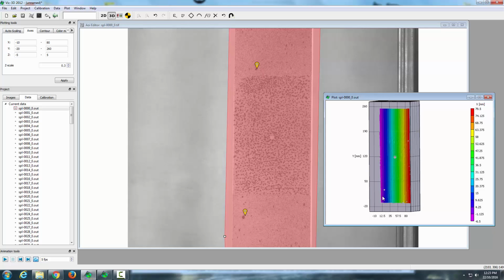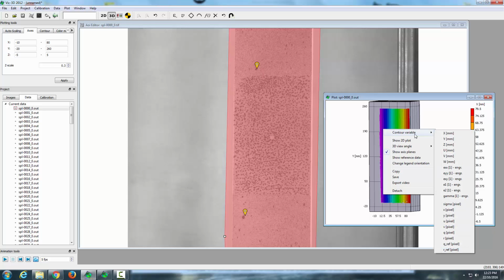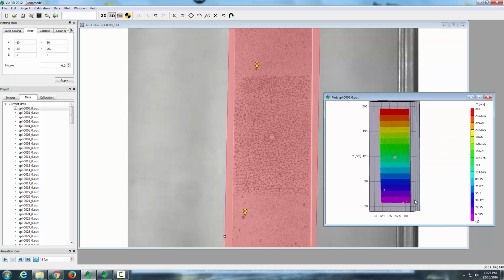Now before, in a previous video, you saw that I did a 3-point coordinate transform, and if you remember, the very first click that I did was down in this area down here, and you can actually see here that the X position does correlate to 0 around about there, and it goes positive from that point onward. The very second click I clicked determined that positive direction, and so that's what we have there. The third click I made, which was up this direction, determined positive Y. So we can have a look at Y, and again we just have a Y position there.